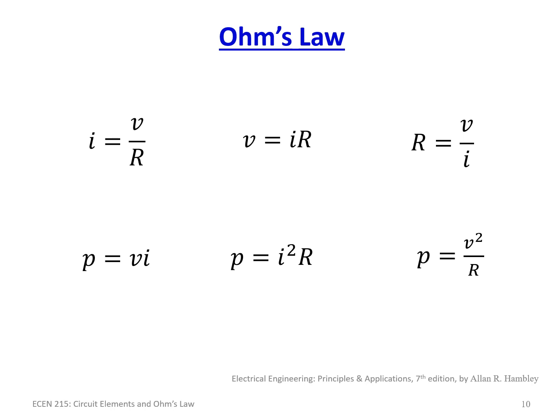So this is probably the one slide of this entire slide deck that is going to be copied and used heavily throughout the semester until you get these equations basically memorized. So, simple algebraic equations: I is equal to V over R, V is equal to IR, or R is equal to V over I. And correspondingly, if you are looking for power, which we defined earlier, it is equal to V times I, in other words, the voltage times the current. Or, if you know current and you know the resistance, you don't necessarily need to compute the voltage, because we just use IR, and that ends up being I squared R.